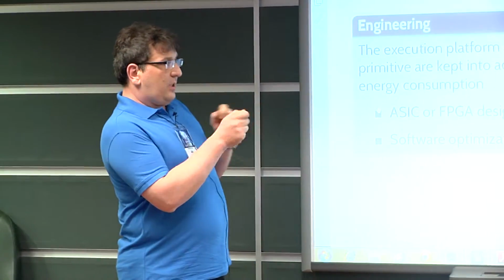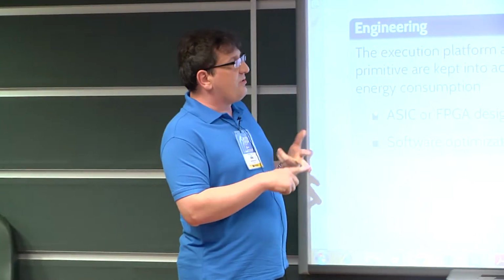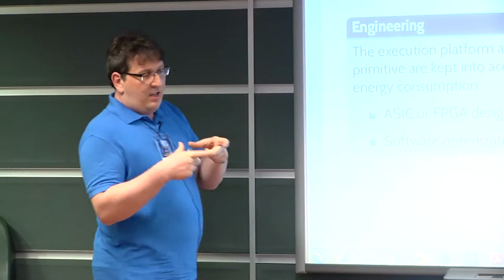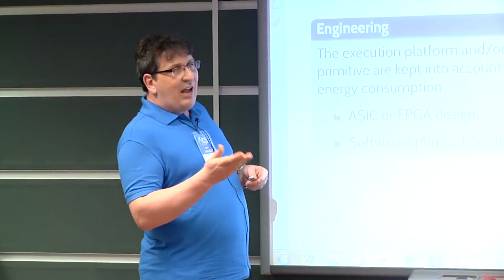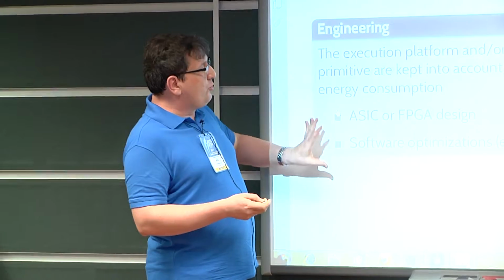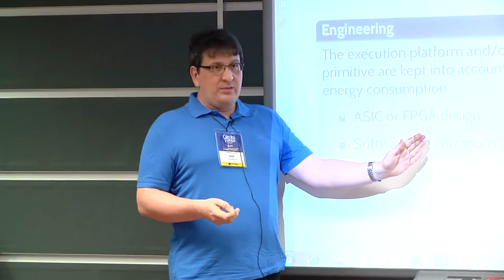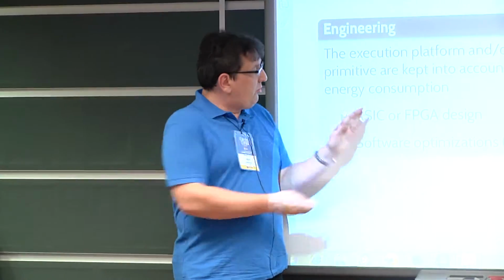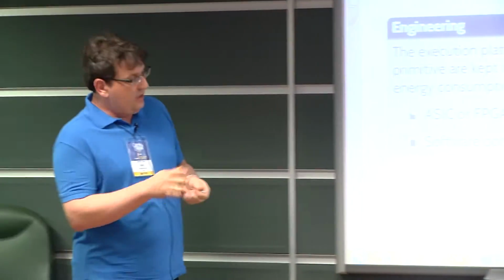So considerations about performance, energy consumption, or the silicon area of your device can drive you, the designer, to choose an ASIC or FPGA design or a software implementation, or both, a solution which is in the middle of these two extremes. Okay, so let's see.